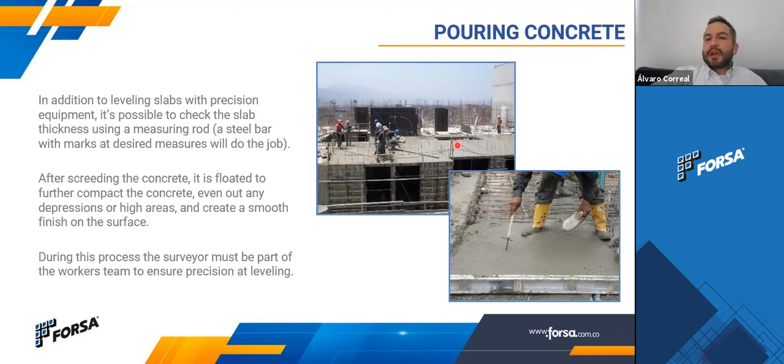Once, after an hour or so, that the concrete has been poured, then you float it, whatever method you want to use. Very important, as I said, to have a very well-leveled slab. And remember, the surveyor at this stage is very important, so have his collaboration and work, and he will be the one checking and telling you if you need to go higher or lower.